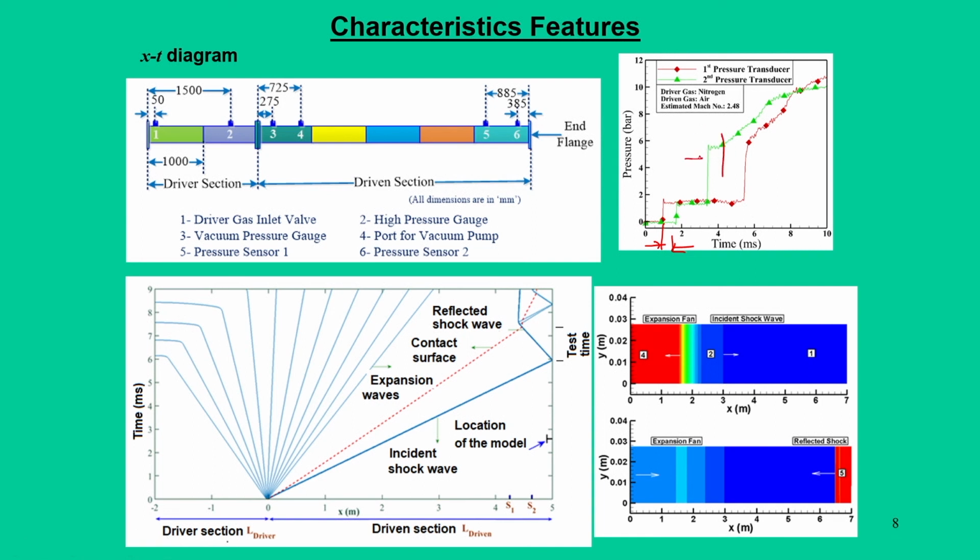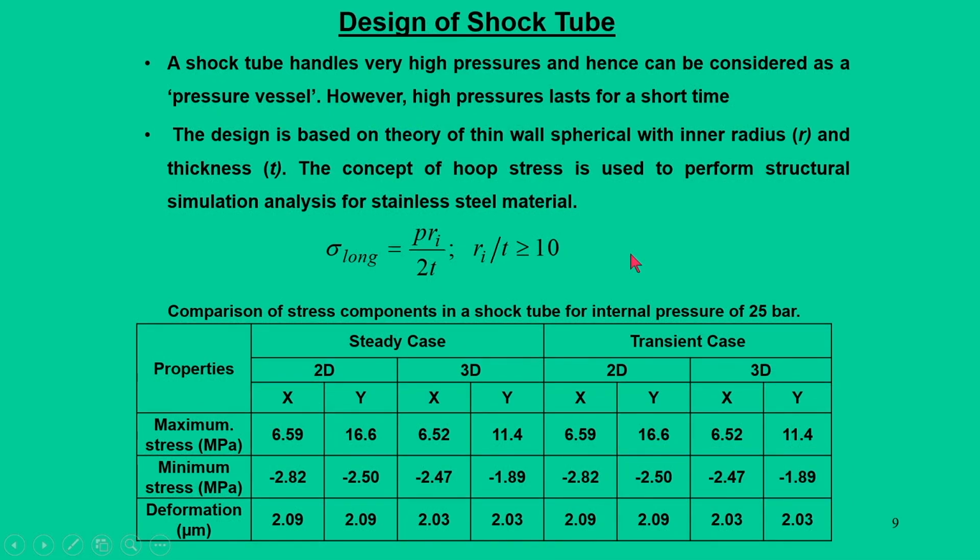One particular transducer has some steady region, about 1 millisecond, and after that there is further rise in pressure, mainly because the entire slug of mass also gets added up, since the contact surface has arrived and the high pressure helium gas has also arrived. So, all these things merge up, and we do not take any data beyond this time scale. So, these are the characteristic features.